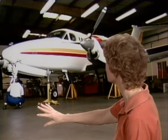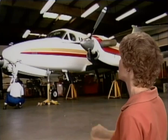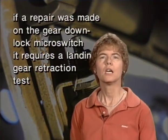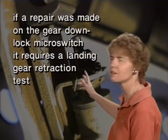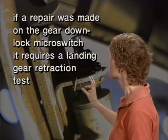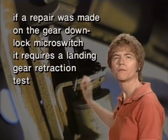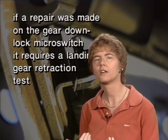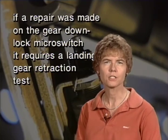So if you've been working on anything that might affect the gear retraction system, make sure and cycle the gear with the airplane on jacks and make sure that it's working properly. For example, an example of a repair that would require a landing gear retraction test is if you made a repair on the gear downlock micro switch. If you made a repair on the gear downlock micro switch, that might affect the landing gear retraction system, and you need to test the landing gear on jacks after that repair is done.